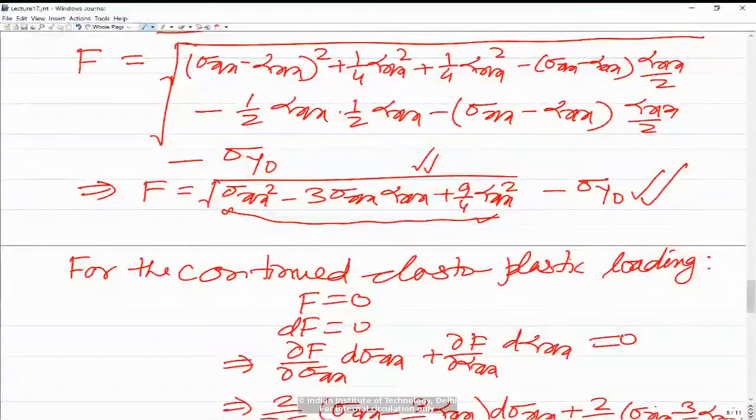We are using the Newton-Raphson method for that B transpose sigma. As sigma is a nonlinear function of strain, in Newton-Raphson we assume some value for x. Which value do we have to assume here? We will start initially with whatever load is there and divide it into a number of steps.